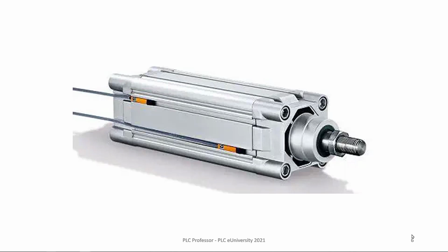If this image that you're looking at, this rectangle, were a piece of copper, and you were passing current flow through it from left to right, typically it would spread out fairly evenly across the whole strip of copper. Or say this is the wire. Typically you're going to have more electron flow in the center of the wire than towards the outside, simply because of something called counter EMF, counter electromotive force. In other words, the magnetic field from the electrons traveling all one direction in the middle of the wire, as that field expands out, it opposes the electrons further out in the wire.